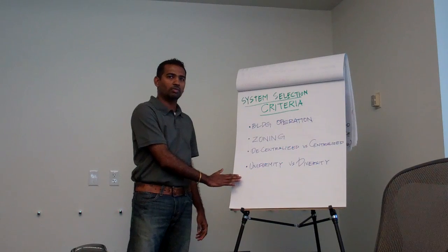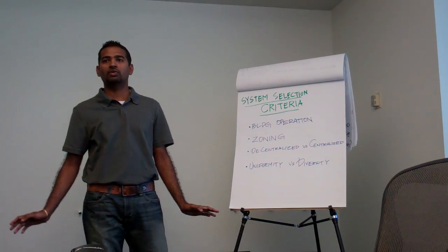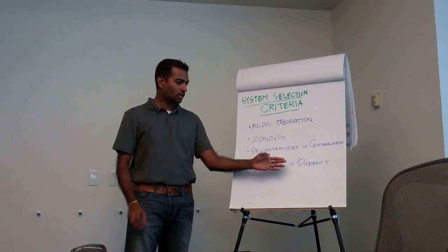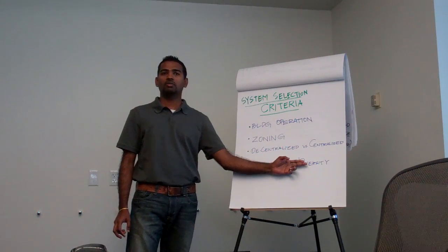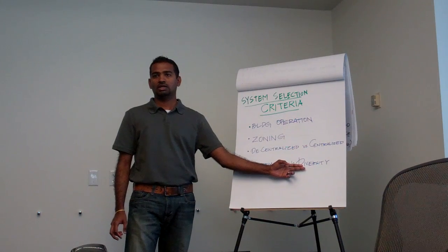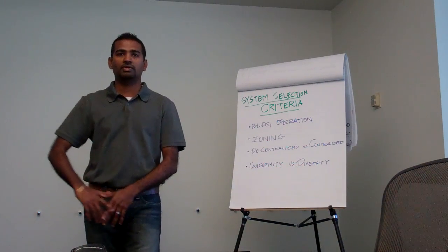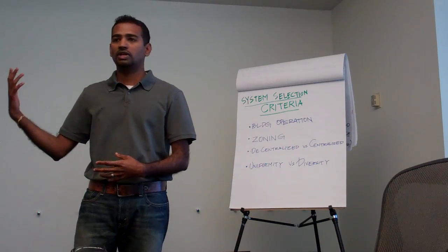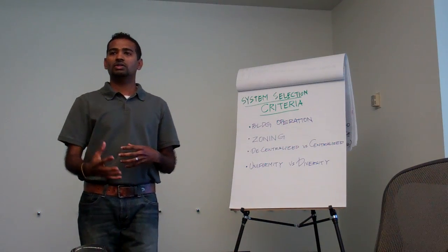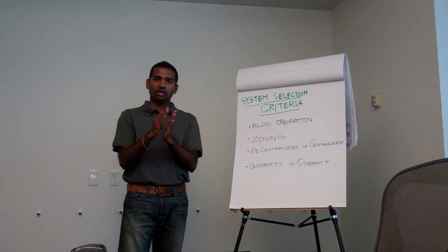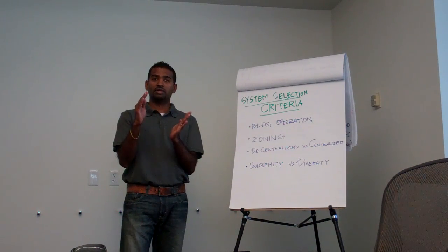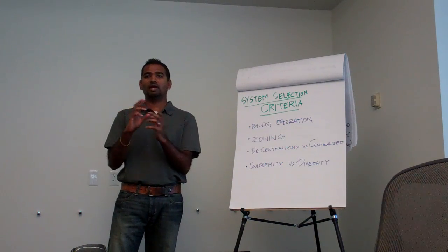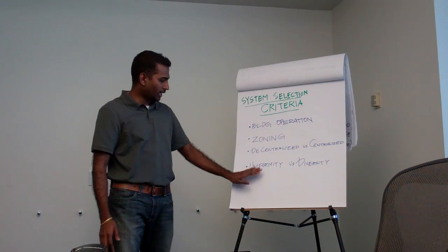If the client says, no, I want 75 degrees uniform throughout my facility, that changes your system selection. On the other hand, if they say, yes, I'm okay to have some diversity, my circulation spaces could have different temperature control, or my gyms could have different temperature control, then by having that range of thermal comfort, that allows for more mechanical systems as options to evaluate. So it is important to ask this question.